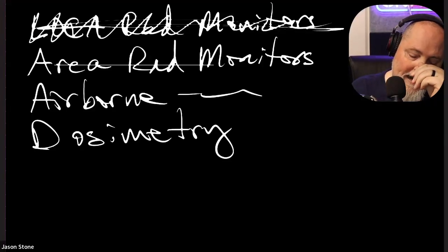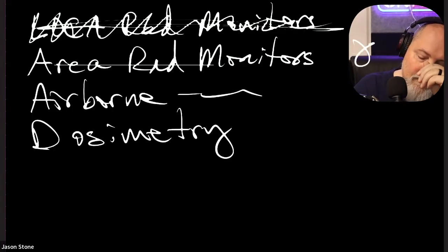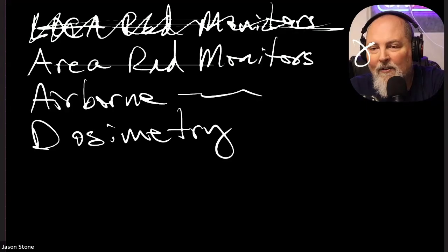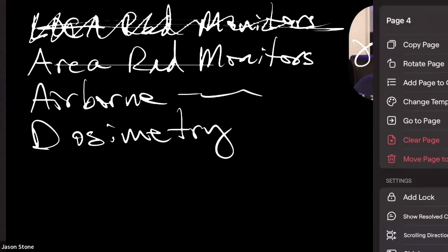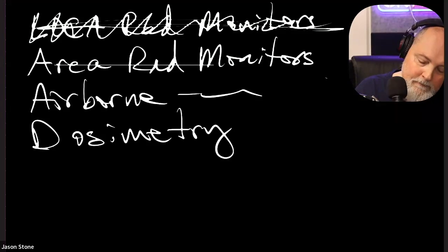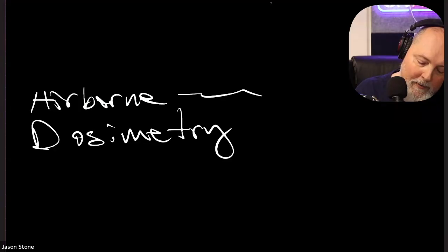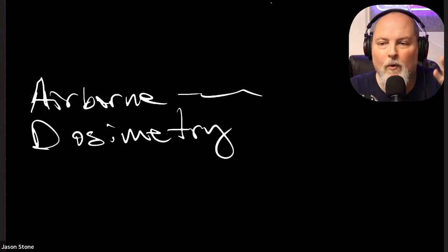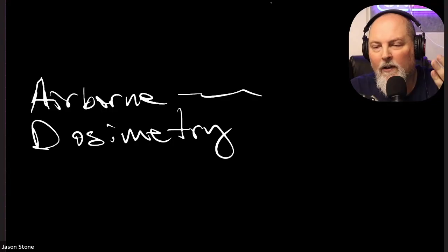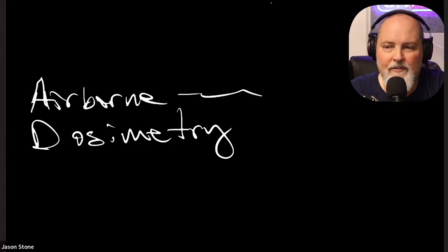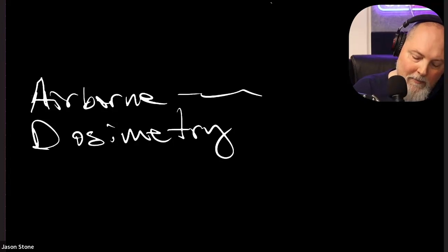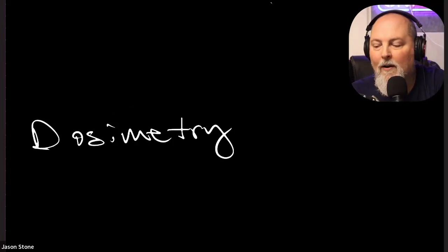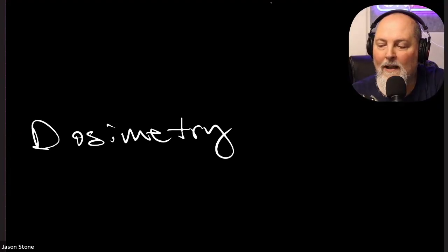And we say, hey, we've got a leak, we've got fission product release. Area rad monitors detect gamma throughout the plant. They're used for access and diagnostics. Area rad monitors monitor gamma radiation levels, and if we say, hey, we need to send somebody in to isolate this thing, what are the radiation levels? They look at the area rad monitors and say, radiation levels are this amount, and they use that to diagnose whether it is safe to send them in or not. And so that's our radiation monitors. We have airborne rad monitors. Airborne is real time. They have real time alarms for airborne hazards.